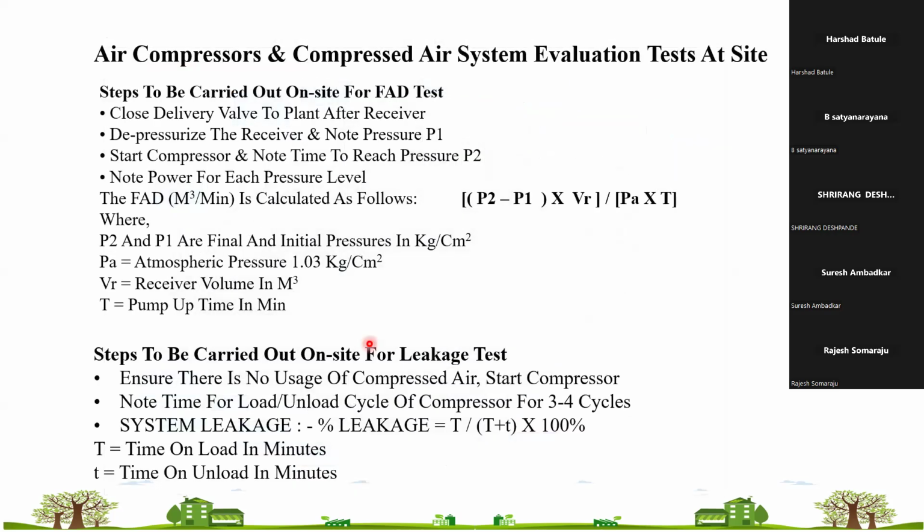So what is free air delivery? Free air delivery is the capacity of the compressor. In typical language, it is the capacity of the compressor. What does this mean? It is the flow of gas compressed, measured at the inlet of the compressor and at your desired pressure.